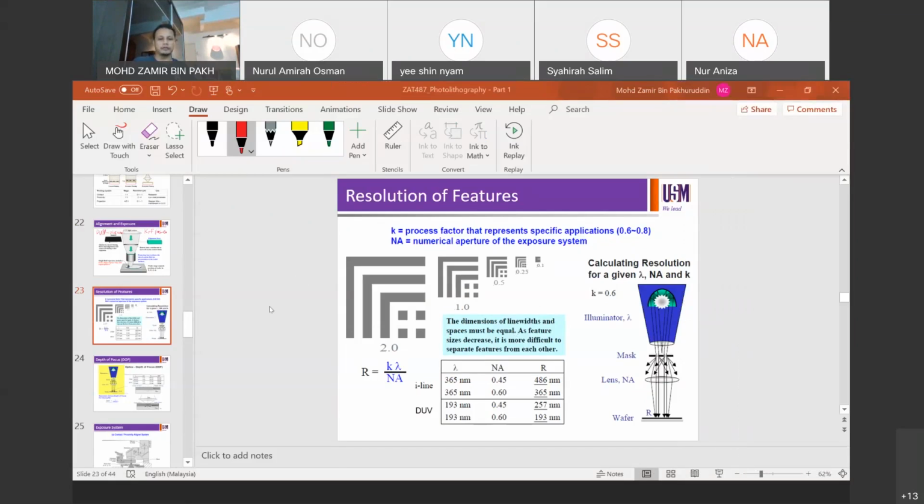Okay, so for example, if you want to print, you have this kind of setup. You have your illumination system up here, for example, UV. Then you have your reticle here. Reticle and mask are the same. But for the advanced system we call it reticle. We don't call it mask anymore. But essentially it's a mask. So it's gonna block the light in certain areas, and it's gonna let the light pass through in some other areas. Okay. Then you're gonna have your projection optics, your lenses and everything down here, and eventually your wafer on the stage. Okay, wafer on the stage.